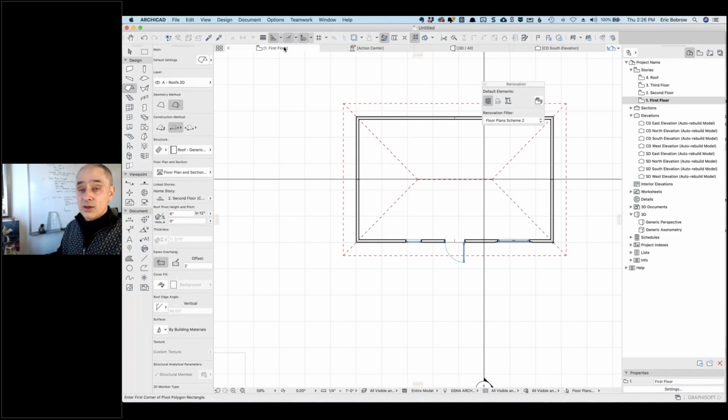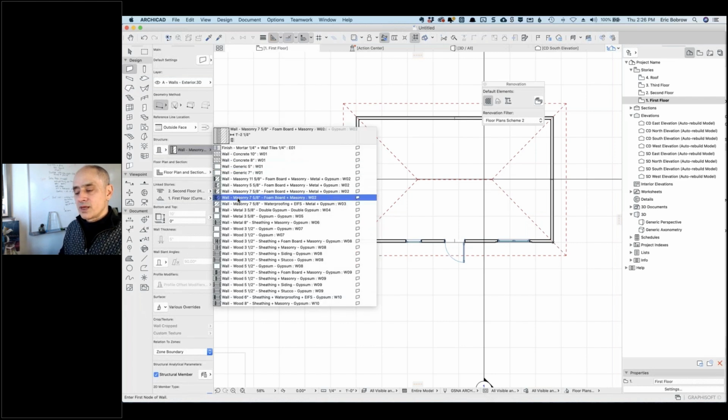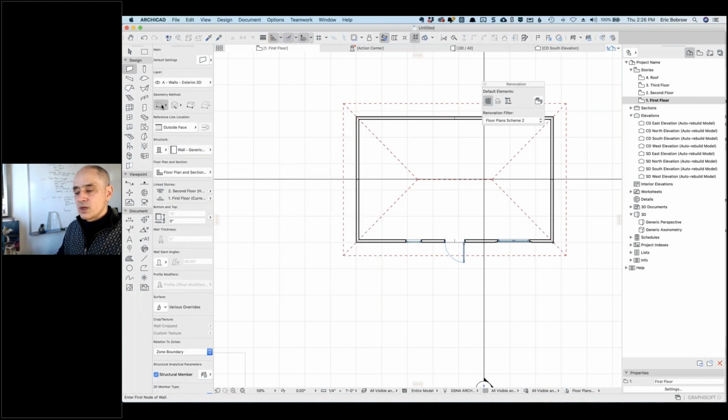Well, one of her tricks that I thought was very cool, I'm going to just demonstrate. When you go to the wall tool, if you have a composite here, you can do straight walls, a chain of walls in sequence, a box of walls, etc. And you can do curved walls. And you can even say, I'd like to have a wall that starts with one thickness and ends with a different thickness, but still has the same outer cladding. But this icon here is gray. It's called a polygon wall.